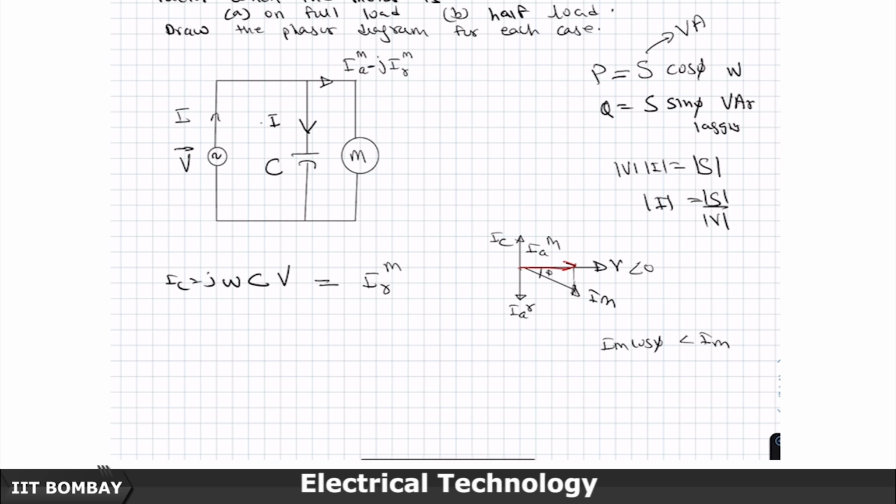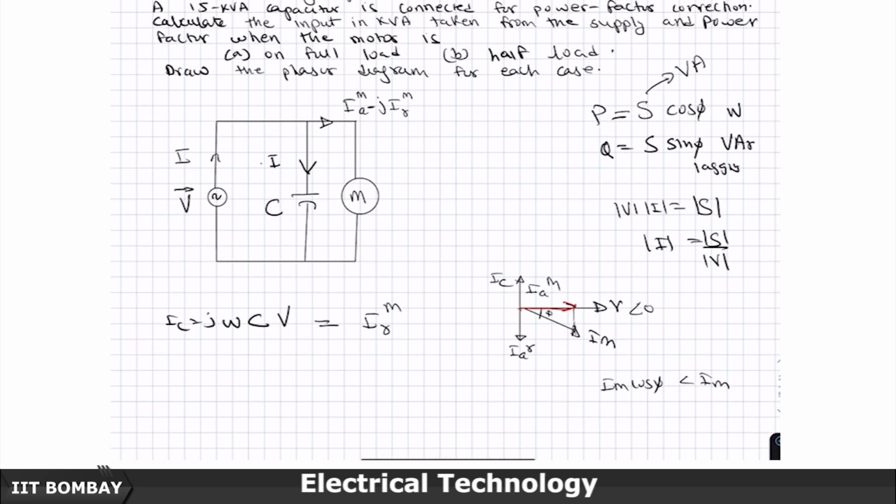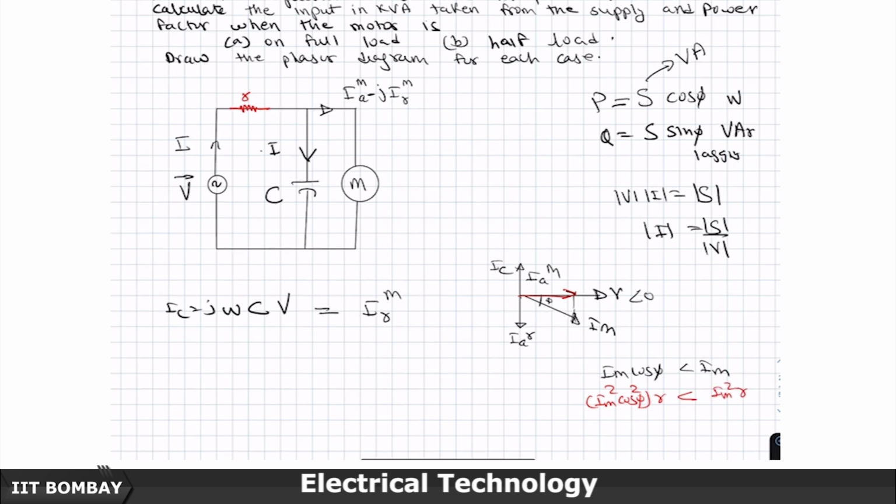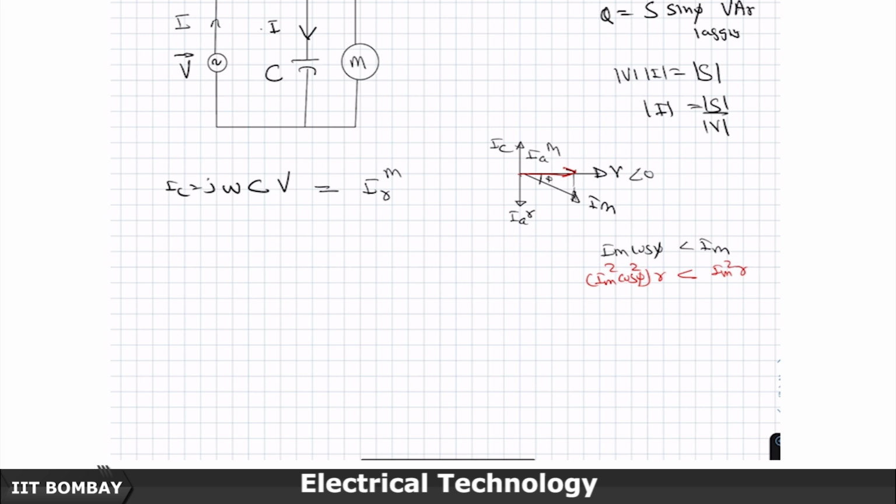So, therefore, suppose this wire had a small resistance, small because it should be so small that my calculations are not significantly impacted, it can be treated as a correct approximation. Then you can see that the new wire loss is so much, while the original wire loss is Im square r. So, therefore, if you look at the reduction in the loss, taking Im square r common,